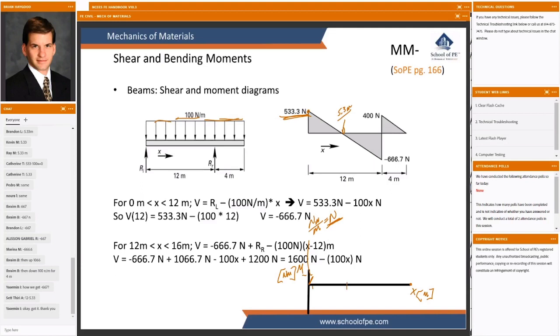So I can come over here to the 5.3 meter mark, and I know my slope there is going to be 0, so that's horizontal. We start with an upward trend, and that upward trend decreases in slope gradually and eventually reaches a slope of 0 at the top. That shape is going to be parabolic. If you wanted to draw it accurately, it's a parabola. It's not a circle, it's parabolic.